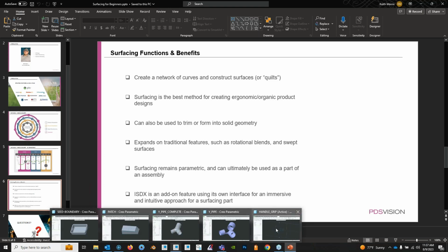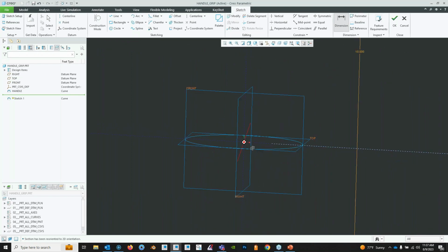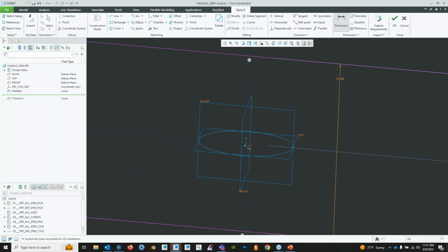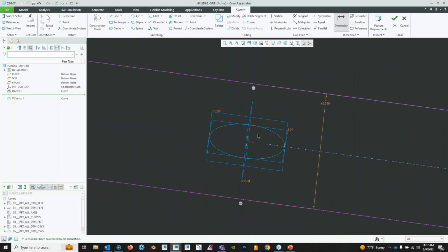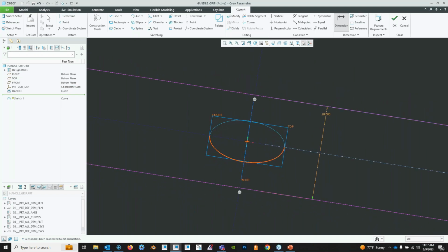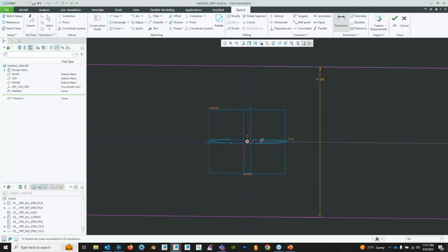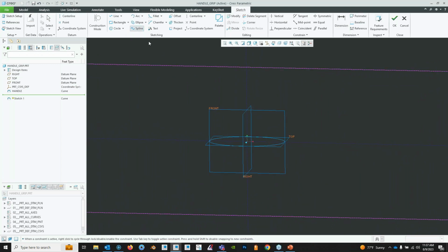We're going to give you essentially the introduction and basics into this. So I already have a part file set up here, and all I'm going to do in here is set up 3 sketches. I already have my first one, which is just an ellipse. Now I'm in another sketch, and I'm going to choose a spline.